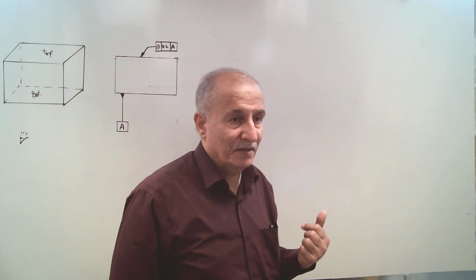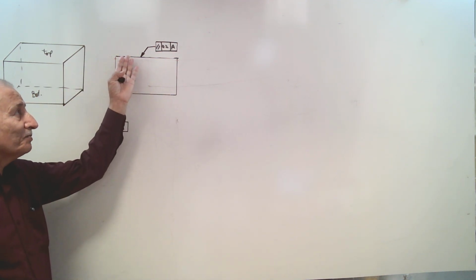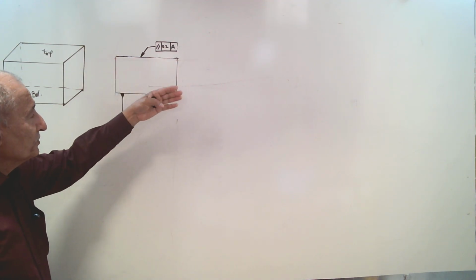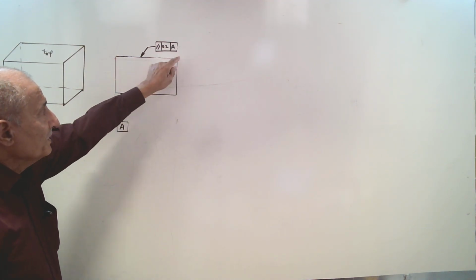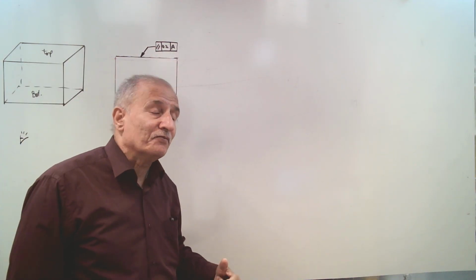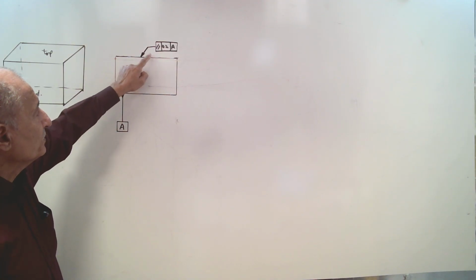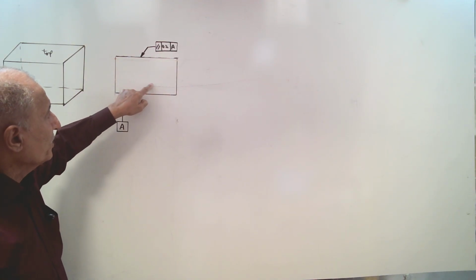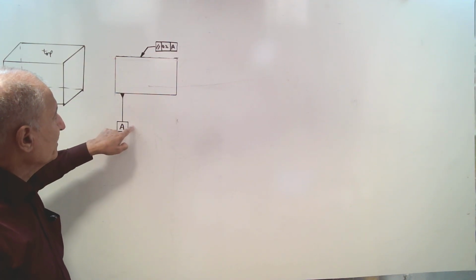Everything that I showed before, the zone shape, which is parallel, the zone space, which is a space between two parallel planes, and the zone size, which was pointed to, is the interpretation of this symbol. This means that the top surface must be parallel, inside the tolerance zone of the given size, to datum A.